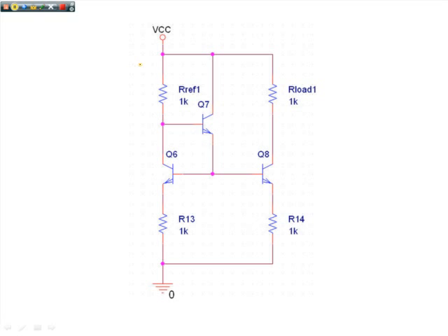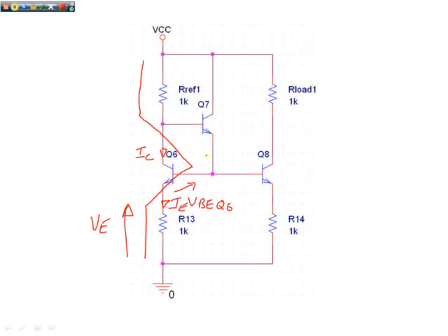Okay, so let's have a look at how we design this circuit. We need to calculate the volt drop on the Kirchhoff's voltage loop from here, through here, through here, and down here. So our Kirchhoff's loop is quite complex. For a start, we're going to have a voltage here, VE, and that's proportional to IE. I'll define what that is in a moment. IC will be here. We have a volt drop here. Let's label that up, VBE, Q6.